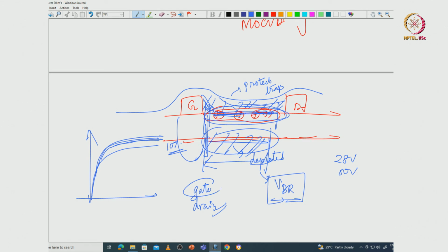the collapse. In gate lag, if your crystal quality is very good, you may not even see a collapse, it will be very minimal, okay. And if your crystal quality is bad, then you will also see some gate lag dispersion. Also, people sometimes see that a passivation also improves gate lag, by the way. So, it is a complicated interplay, and a good passivation scheme is not very easy, because it will depend on whether the silicon nitride that you are putting is tensile stressed or compressive stressed, for instance, what is the refractive index of the silicon nitride. All these things will matter in terms of coming up with a very good silicon nitride passivation recipe to protect